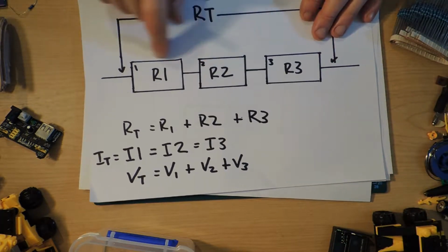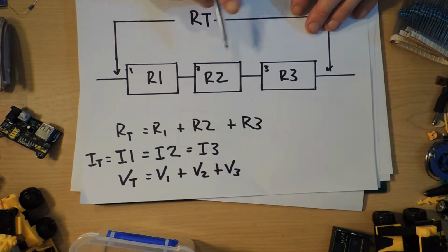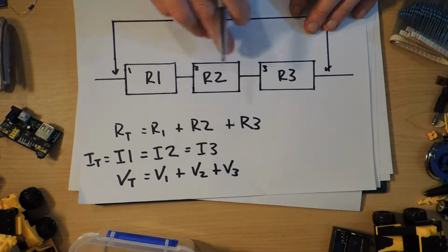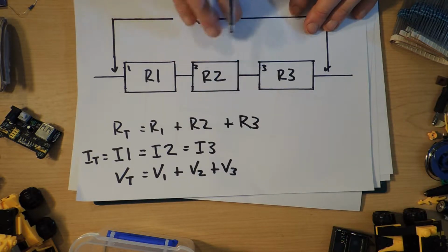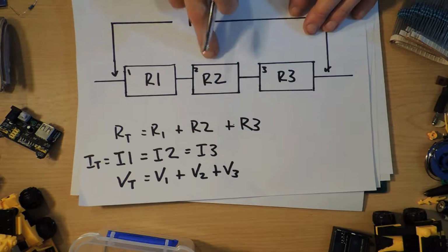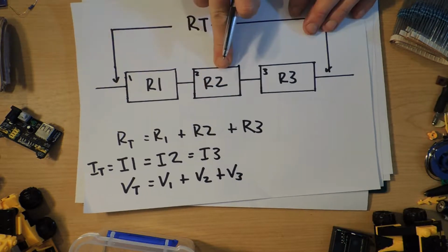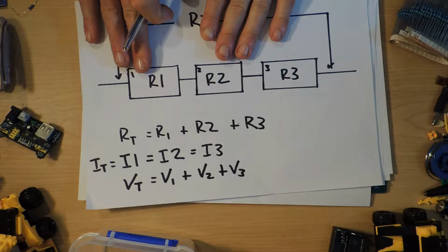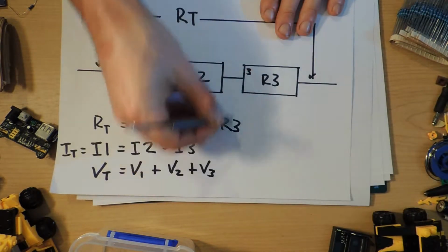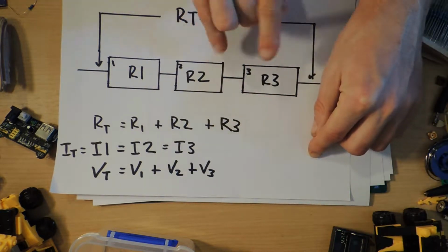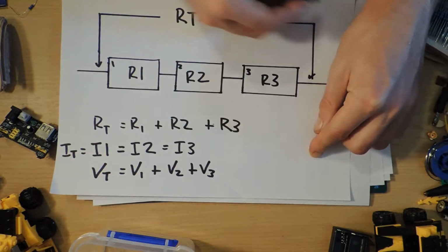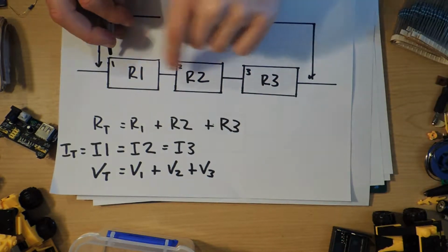Okay, and in most cases, the thing that is really important in series circuits is that it doesn't matter which way around these things usually go for most components. Well, for all the ones that I'm going to be talking about anyhow. If this resistor was over here and that one was over here, it would still be exactly the same kind of effect in the end. It does matter, of course, if things split off from that point there, then you can't swap those two around and get the same result. But if they're all like here and there's no branching off, then it doesn't matter which way around these things go.